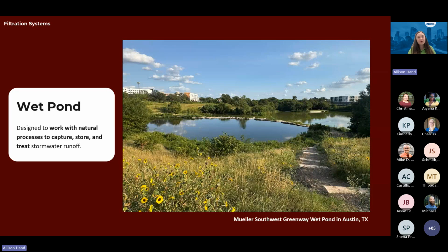Okay, so a wet pond is where we'll dive deeper. A wet pond is a type of engineered basin used to treat and retain stormwater runoff, providing multiple benefits related to flood mitigation, water quality improvement, and ecosystem support. By maintaining a permanent pool of water, wet ponds improve water quality by allowing sediment to settle out of the water. Using additional detention volume stacked on top of the permanent pool, wet ponds reduce and delay peak flows to mitigate flooding. Constructed wetland cells are often design components of a wetland around its fringes.